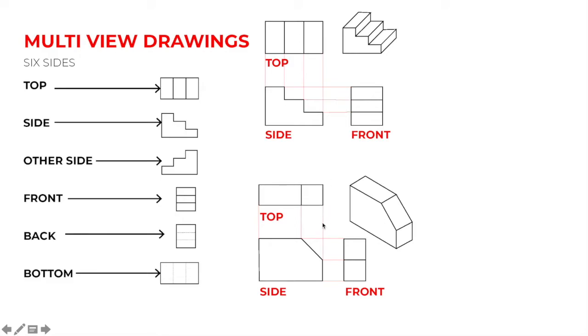Here's a little curveball now. So here is a rectangular prism that has a chamfered edge or beveled edge. From the top, you can't see the bevel because we're looking directly down at that edge there and then the front edge there. You can't tell that it's beveled whatsoever. Same with the front elevation of this figure. If we were to line that up perfectly, you can see that that's in fact a diagonal edge or an angled edge. That's not visible from the front elevation or the top.